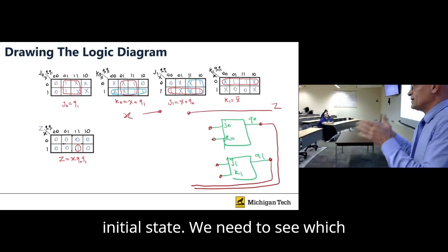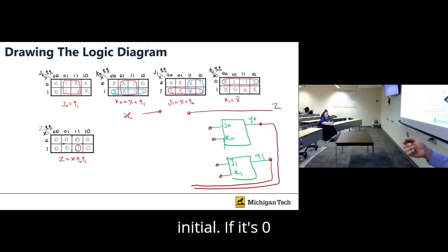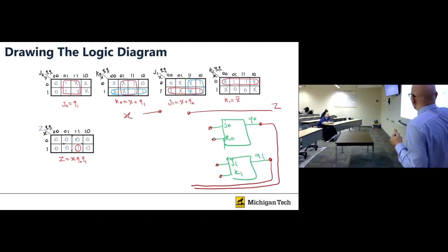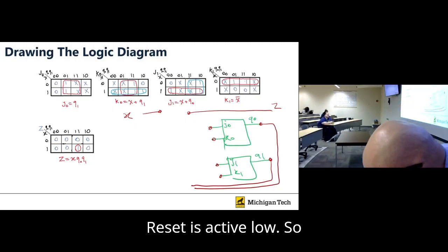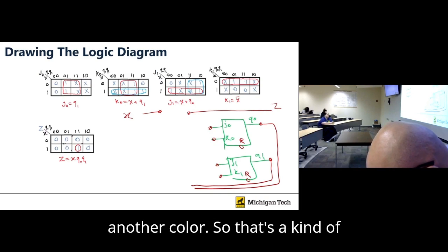We need to see which state is the initial. Here we consider 0 initial. If it's 0 initial, you need to just put them all reset. And reset is active low. So imagine this is reset 1. Let us choose another color.